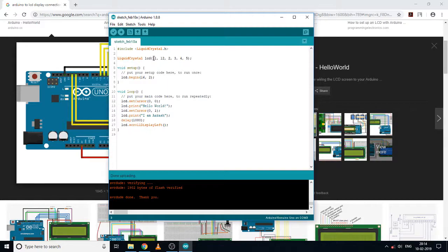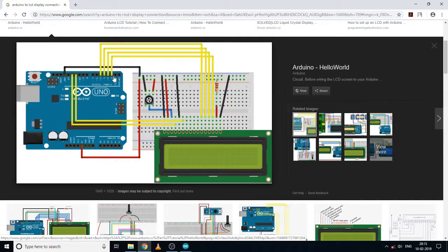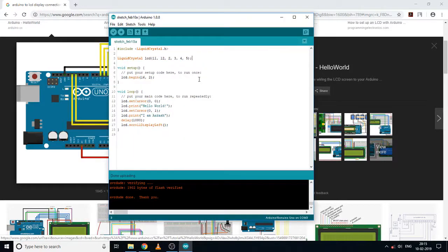So it's not compulsory that you have to specify just these pin numbers that I have specified here. So you can connect these GPIO pins in whatever way you want, but then you will need to change the pin structure that you have written here. So it's not a problem if you know the pins that you are connecting.